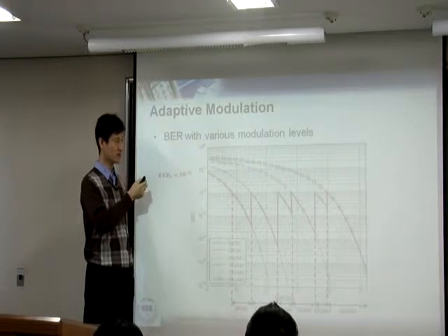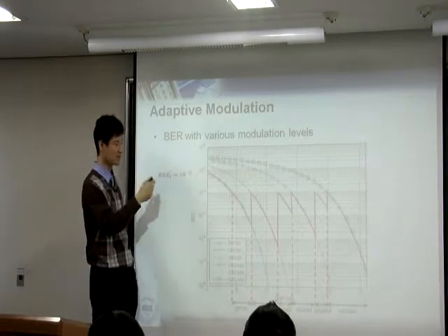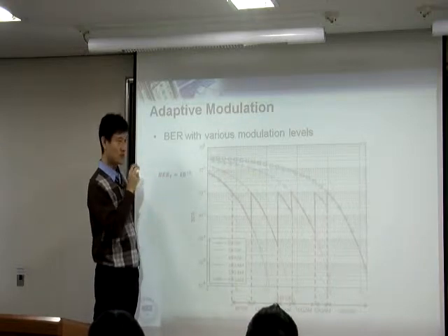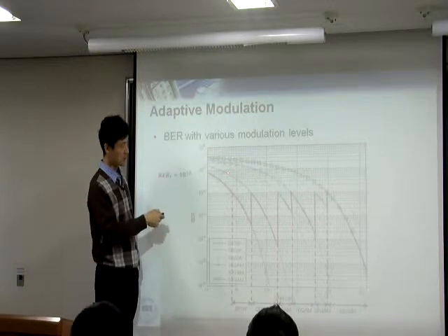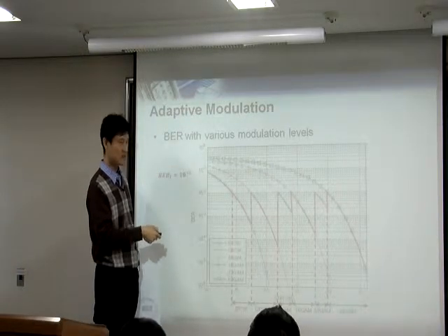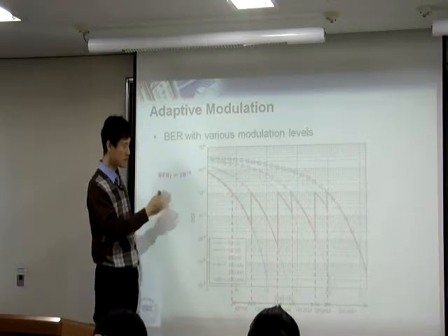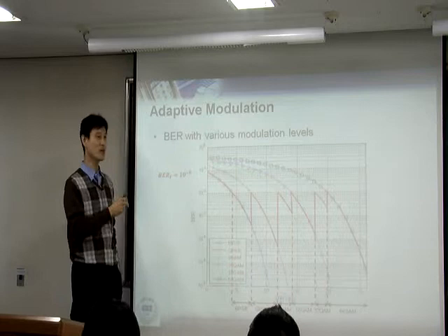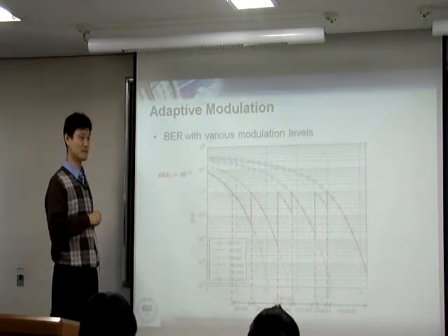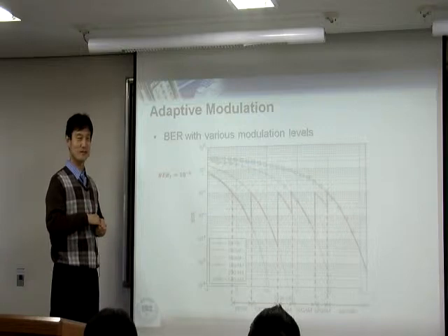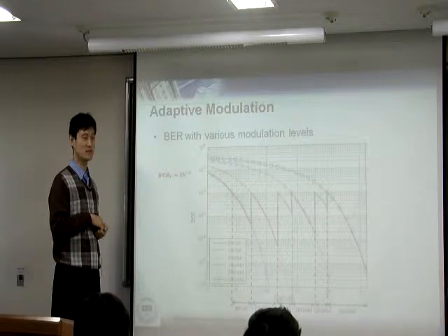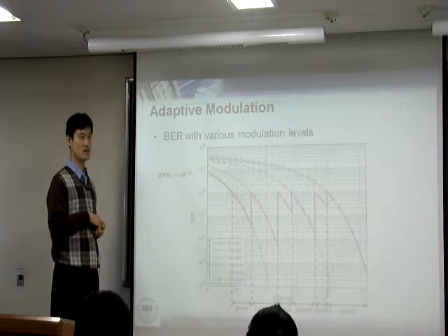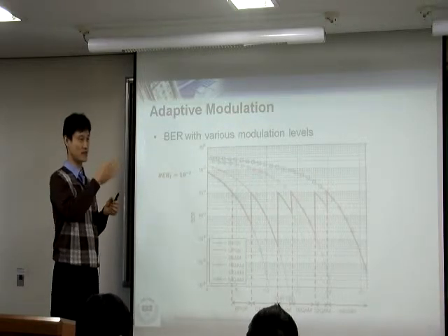That's an interpretation from this picture. When we have this picture, yeah, that's true. If we had a BER, bit error rate, then this blue curve, BPSK, and this red curve, QPSK, must have been the same. These two should be the same. But my question actually is why do we have to use symbol error rate, not bit error rate? Because we are on the channel, not at the end. After that, we get the bit error rate. So that is on the interface, you can say the air interface. In the channel, we are estimating the channel at this point. So our interest is the channel, right?